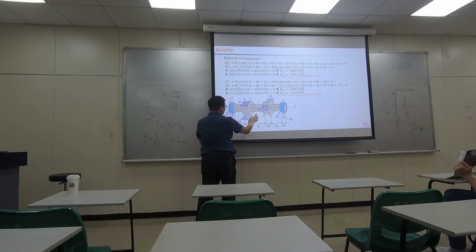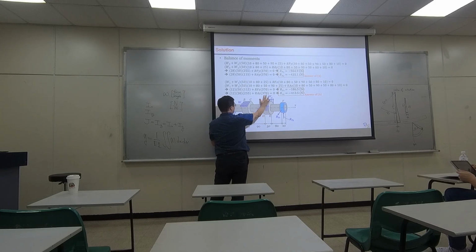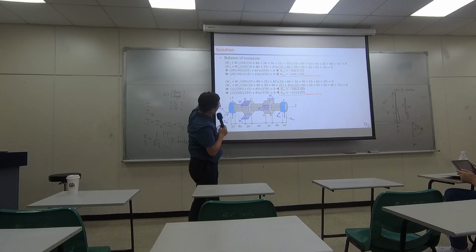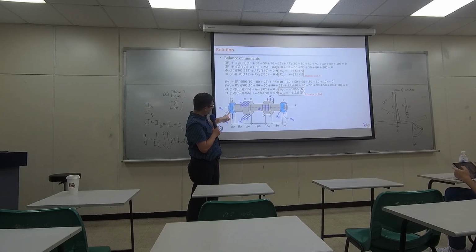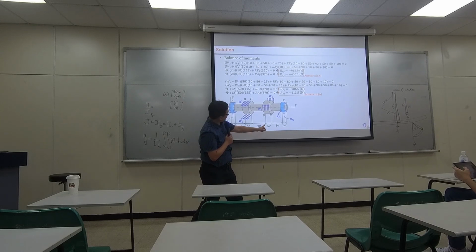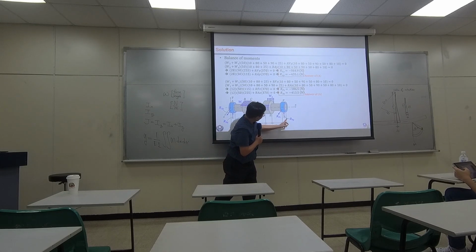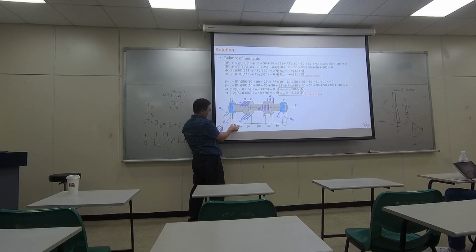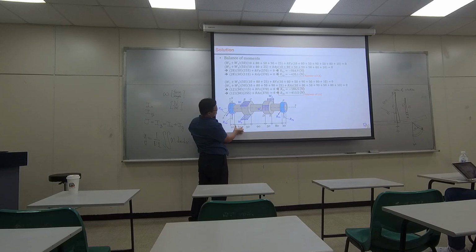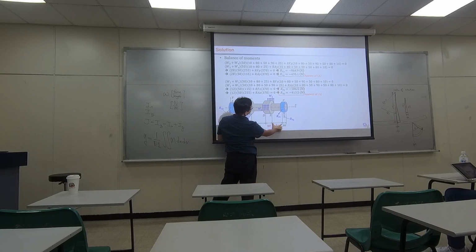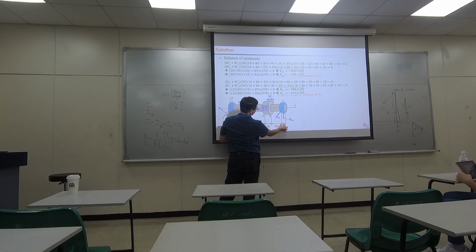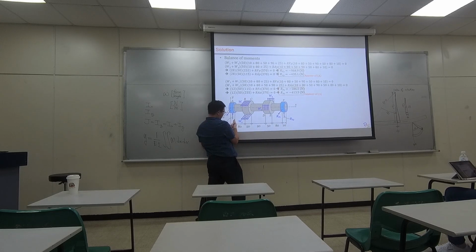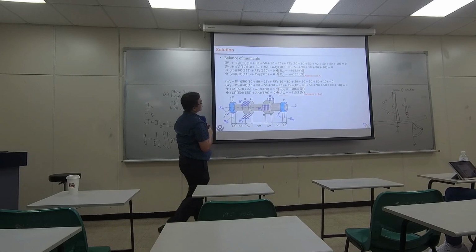So that's the true distance of this force that is generating a counterclockwise moment about this point A. And then RFY is also going counterclockwise. So 10 right here because only half. 80, 50, 90, 50, 80, and then 10. Only half right here. So RFY times the entire distance from this arrow to this arrow. So that's your first equation.